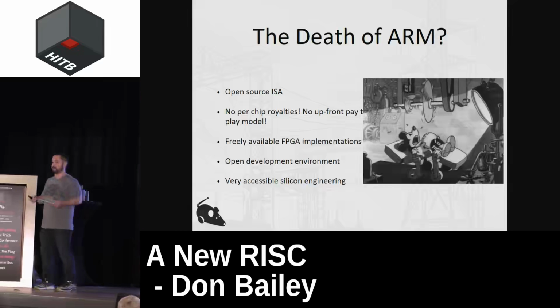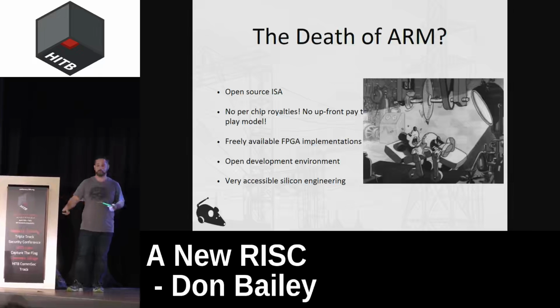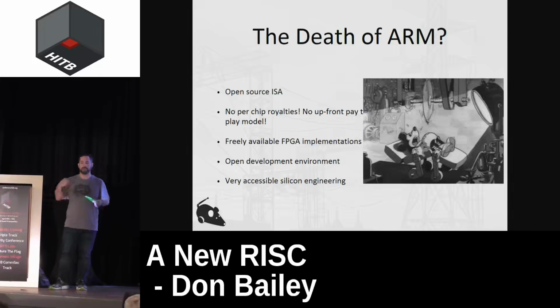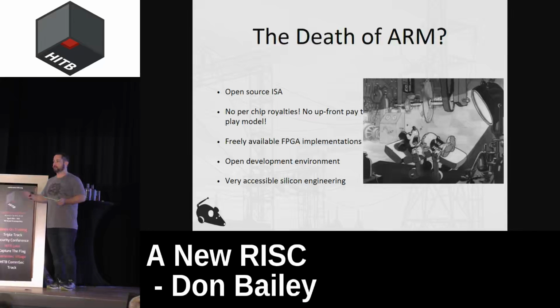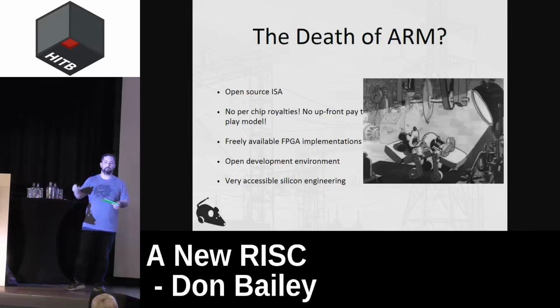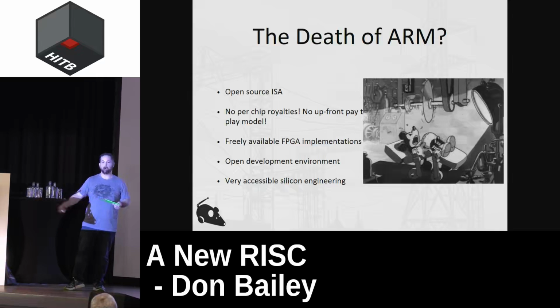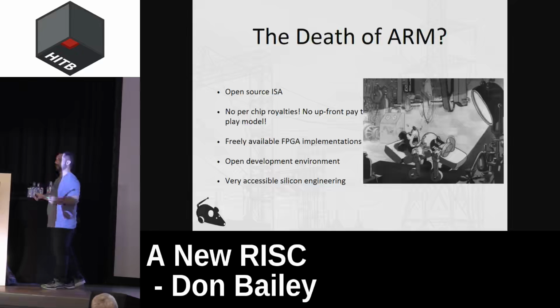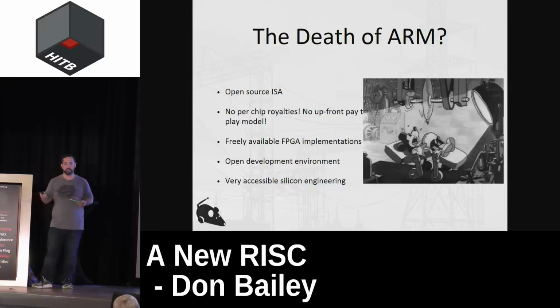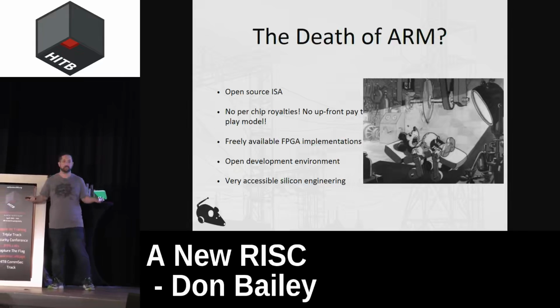If you want to incorporate TrustZone into your chip, you're going to have to start paying 4 times as much as what you would for an M4F. But now you have a TrustZone involved in your chip, and you've basically edged out any of your competition, or allowed them to gain a foothold on your technology if they don't care about security at all. If they don't need TrustZone and they don't want a Cortex-M33 or Cortex-M23, then they're basically going to say, well, we're going to go with the Cortex-M3 for basically a quarter of the cost or less based on volume, and we're going to beat you every single time.